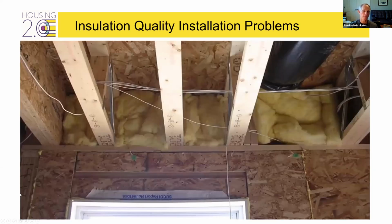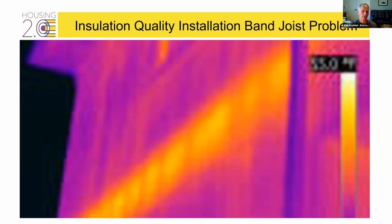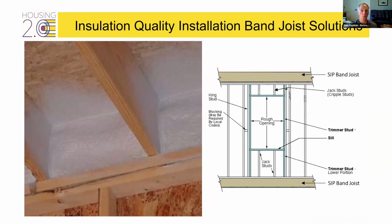And then we have to really figure out solutions for the trouble spots. We know band joists are hard. For instance, they have gaps, voids, compression, and misalignment, which is in effect no air barrier when we use fibrous insulation in the band joists. And that means moisture flow, vapor flow can get to that outside cold surface. So we have to have solutions for these challenging points. They show up in infrared images as a glaring defect if they're not done right. So either spray foam or a SIP band joist are great solutions that we have to start making mandatory in